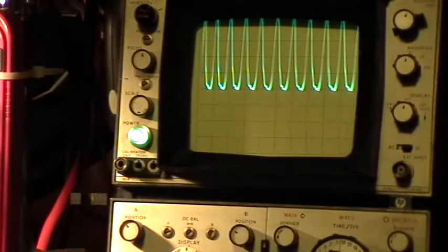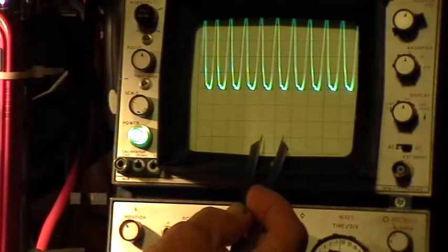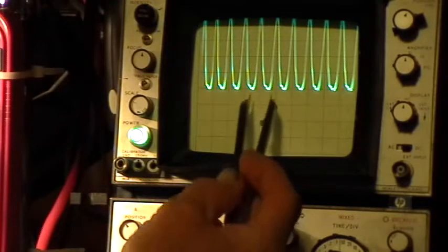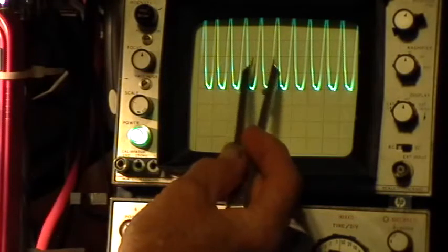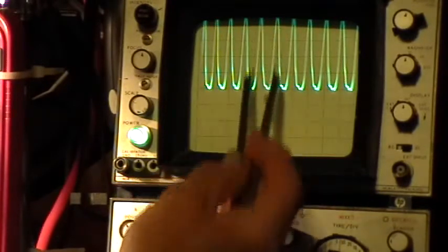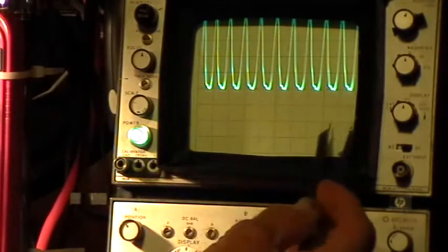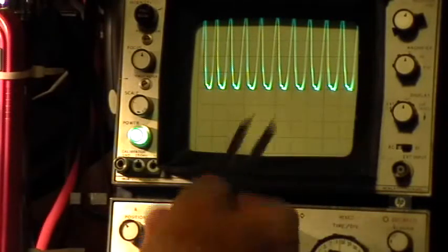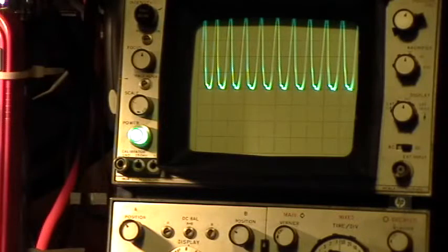So remember the battery voltage is 47.3. We're at the common MOSFET drains. So here's 0, 10, 20, 30, 40, 7.3. So we've got oscillations going plus and minus the battery voltage somewhat, but it doesn't come anywhere near going negative down here, right? Now I'm going to move the probe to the positive rail at the board.